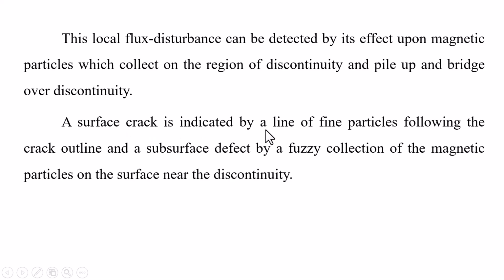A surface crack is indicated by a line of fine particles following the crack outline, and a subsurface defect by a fuzzy collection of the magnetic particles on the surface near the discontinuity. This is the magnetic particle inspection test.